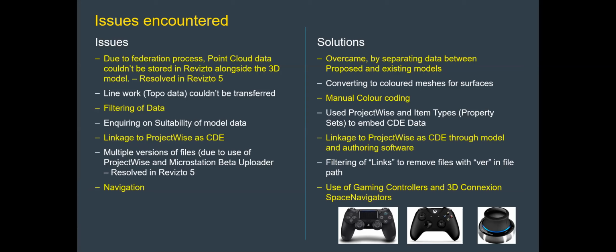So the way ProjectWise and MicroStation-based software has worked with Revizto 4 is that it maintains a link to where it's saved on the C drive when it goes into Revizto. That has meant that we've had some superseded versions come in, but we filter it out using a search filter for version in the file path, and then gets rid of it. Again, solved in Revizto 5.